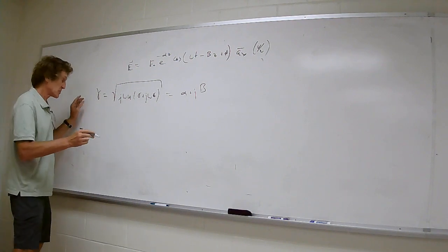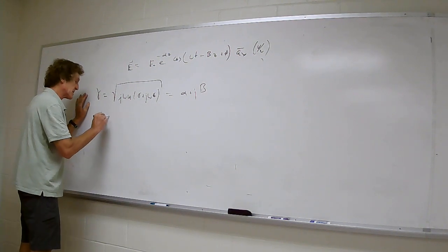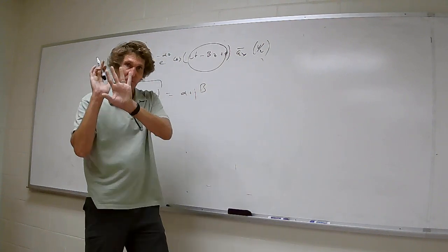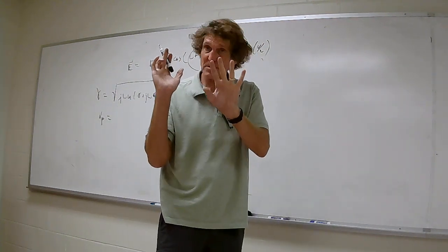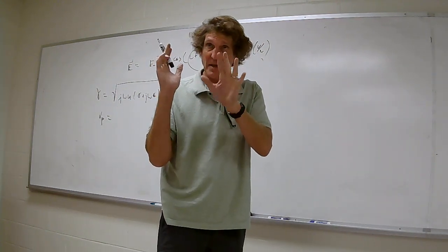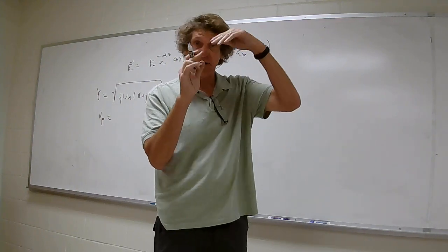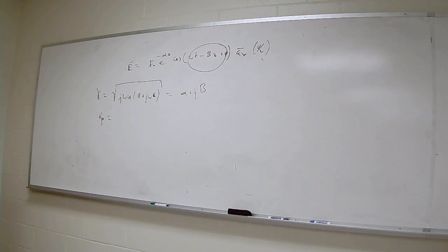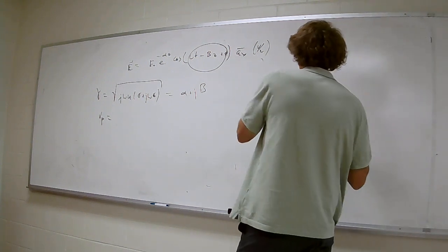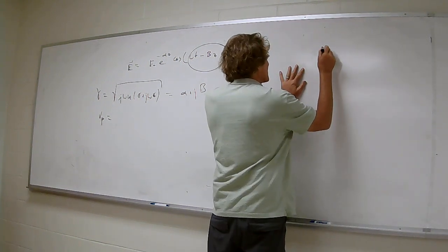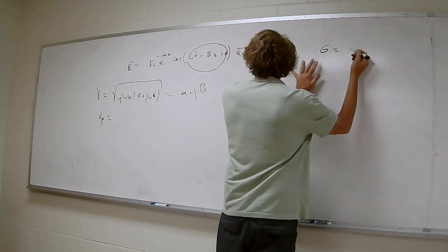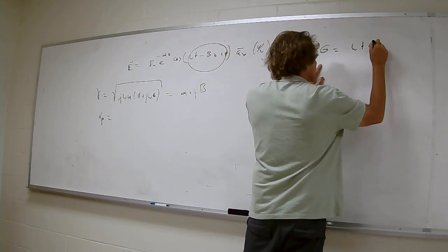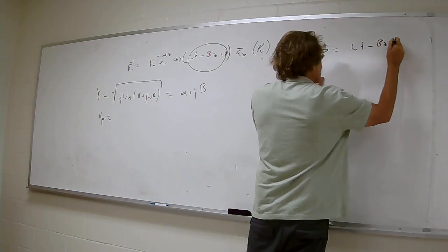You'll see this. So in general, the phase velocity is the rate that the phase of this thing is moving. Think about that. If that's constant, that means the cosine of that is a constant, or that we could just surf on top of that point at a certain velocity. So here, I'll just call this equal to omega t minus beta z plus phi.